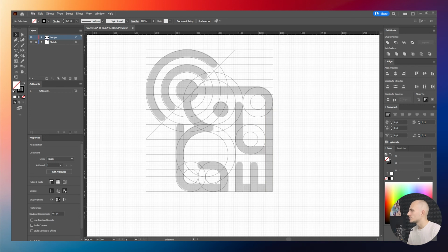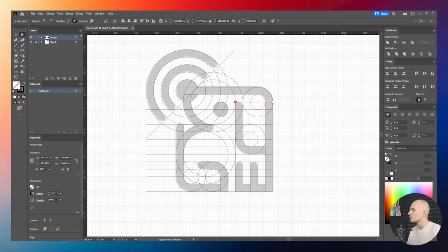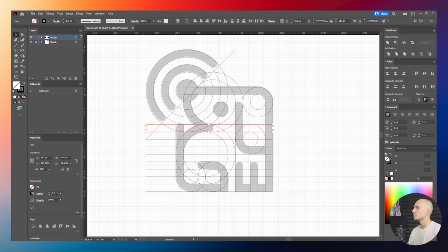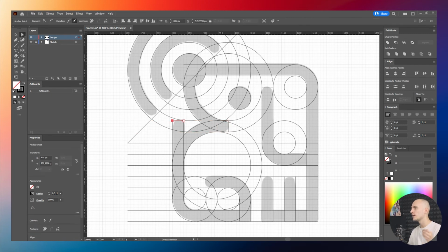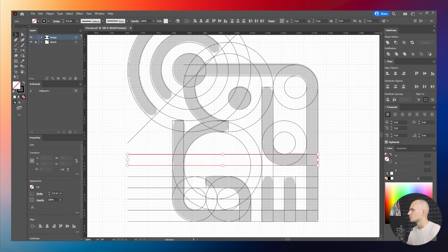Let's now start adjusting the horizontal lines. Removing the first four, they aren't needed. The following ones refer to the top of the head. Let's adjust to fit. This line is for the ear. Delete the next two. With these two we merge the head and back, but at the same time it refers to the tip of the tail. I suggest making a copy of it, Ctrl+C and paste, Ctrl+Shift+V. We'll use one for the tail and the second for connecting the head and back. This one isn't needed. Let's adjust this to the rounding of the lower part of the ear.